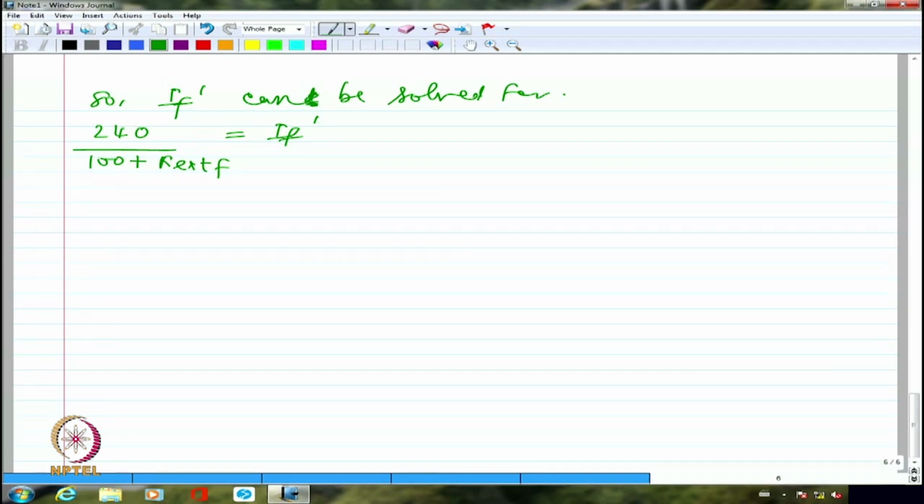If you look at the next subdivision, with field resistance as in A, now the field resistance is 100 plus R external F. Right? Always these are ratio and proportion kind of problems, most of them. So if the field resistance is increased as in A, find the speed when supply current is 100 ampere. You have the field current now, IF dash.